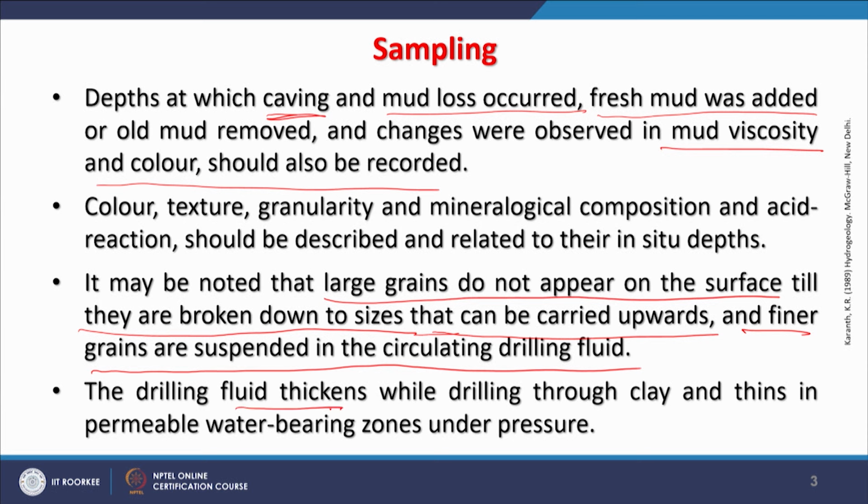Drilling fluid thickens while drilling through clay and thins in permeable water bearing zones under pressure. If water is found, then the viscosity of the mud which is coming will reduce, and an expert driller will immediately tell that he has encountered the groundwater table. That kind of expertise is required. Just by looking at the viscosity of the mud, he can assess a lot of information.